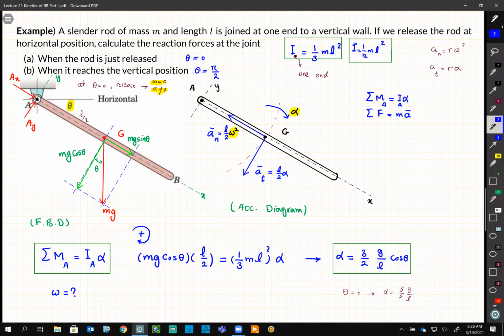And when we say design for a bearing, we don't actually design bearings, we just go to the tables and pick one bearing. Based on the forces that we have, I say, okay, my force here is 1,000 Newton. So I look up the table and I see, oh, okay, I need this bearing. And then there are catalogs, which we look at, and we buy one bearing so it doesn't fail.